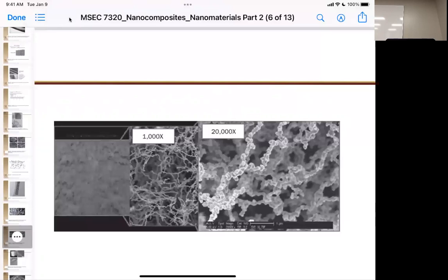Now, you can do that a couple different ways. I've done it with just rastering the SEM. Crank up the voltage on your SEM, raster it out. You have a polymer that'll blow off. You can etch down a couple nanometers and get this three-dimensional structure. But a lot of them do it either by thermal evolution or through sintering processes.